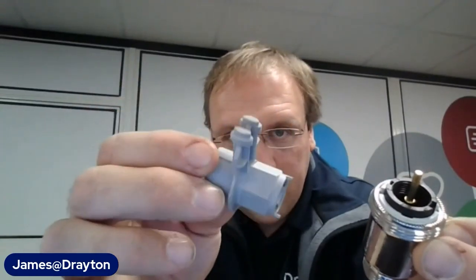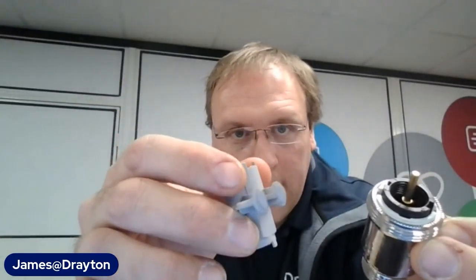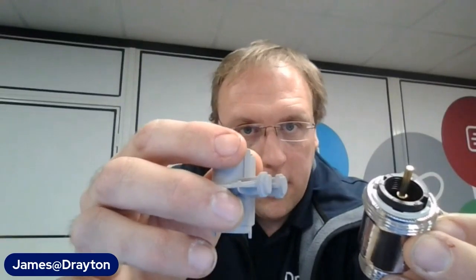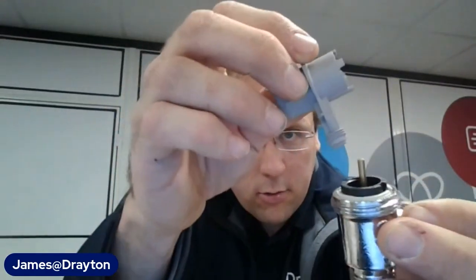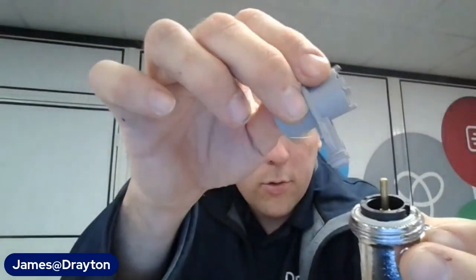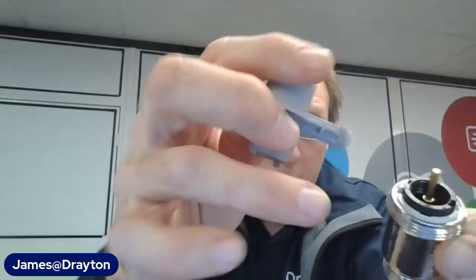I would probably just put a rag underneath so that if there is anything in there, you may get the odd drip, but it's certainly not going to be under any sort of pressure. So you can replace the gland seal on a live system, and to do that you would use this, which is our pre-setting tool. So you would use that end that fits into the gland seal. Once you've taken the old one out, screw the new one down until it's flush with the top.